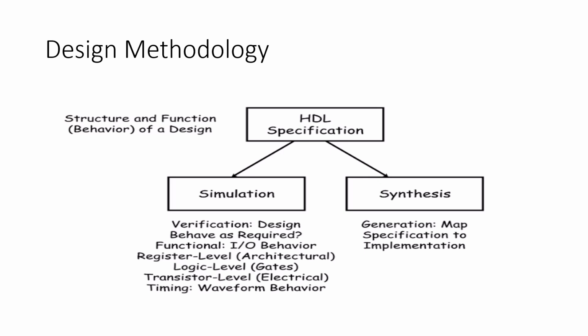The next step is coding, that is, we write the Verilog code. After writing the code, we simulate it. The simulation checks whether the circuit works correctly using a specific simulator. After simulation, we do the synthesis, which converts Verilog into actual logic gates.